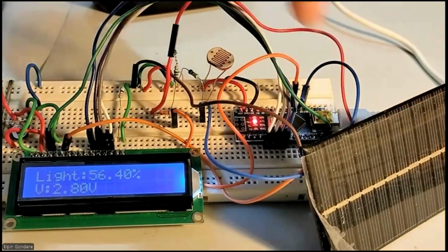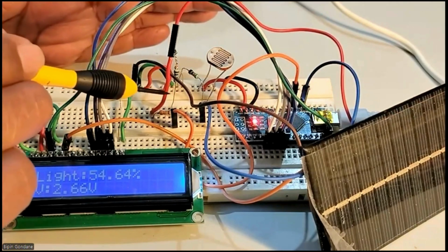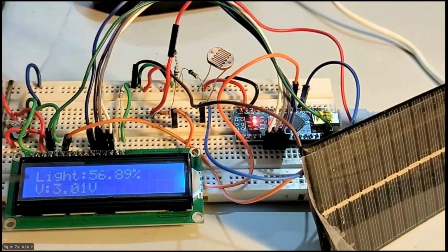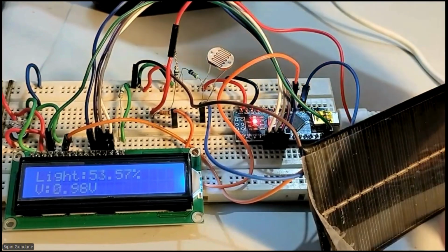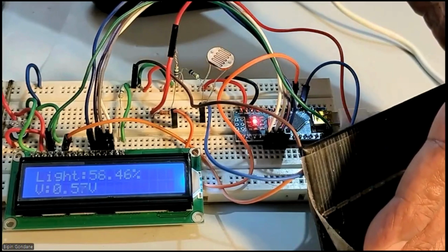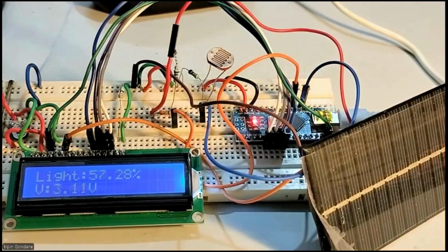Okay, now the voltage divider part. From the solar panel, we have made a voltage divider over here using this. The voltage it is showing is 2.96, 2.74 volt, frequently changing. Again, if I put my hand a little over the solar panel, you can see the voltage has come down to 0.6. As soon as I remove it, the light is more on the solar panel, naturally the voltage is also more.